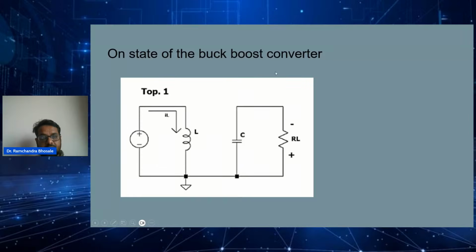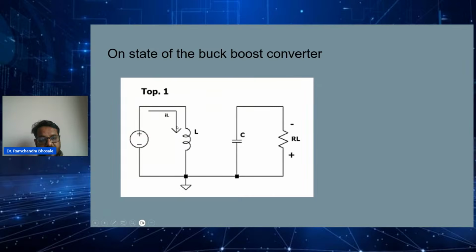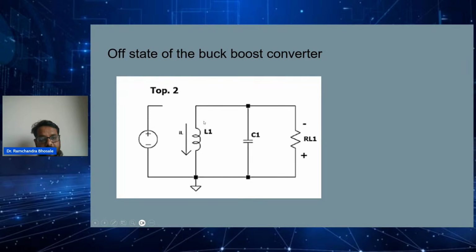Okay, so this is the on state of the buck boost converter. When you turn on this switch, it will charge the inductor, and meanwhile the capacitor will feed the load. And when you turn off the switch, this inductor will feed the capacitor and the load. So this will charge the capacitor like this.